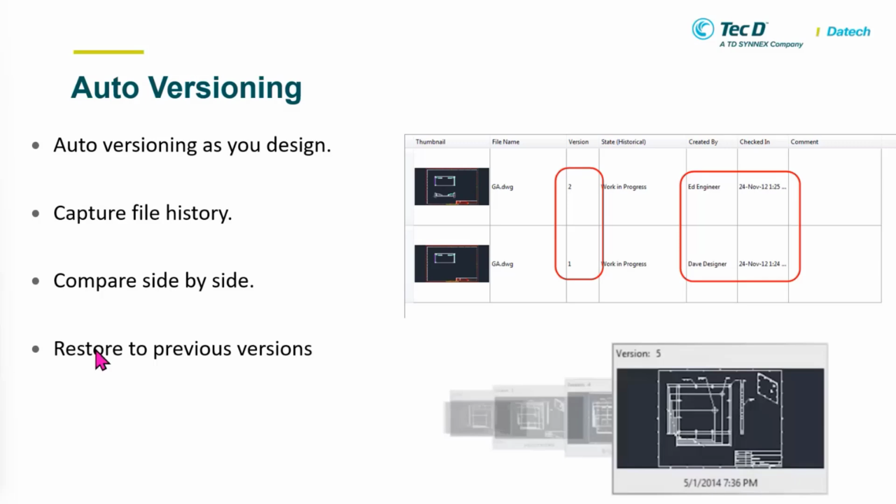So in the case where we always save new versions, the older version is not replaced. It is still stored in Vault. Okay, the metadata is still stored. So every time we want to revert back to older versions, we are able to do it because Vault is maintaining the files for our usage.